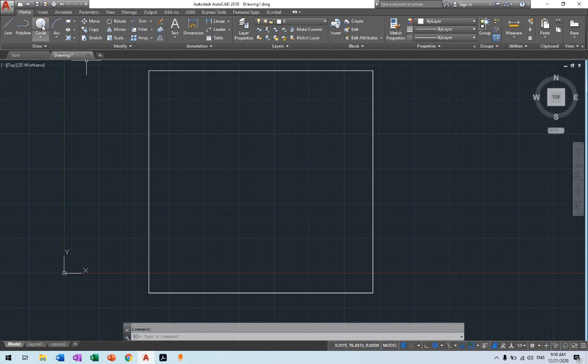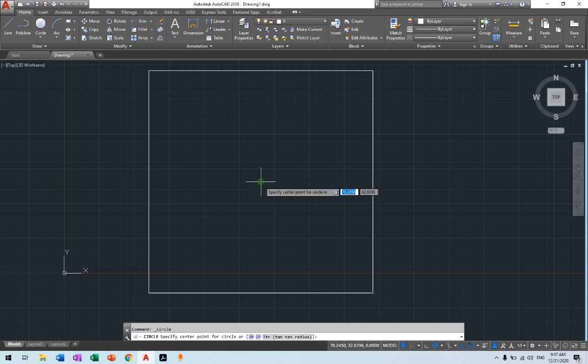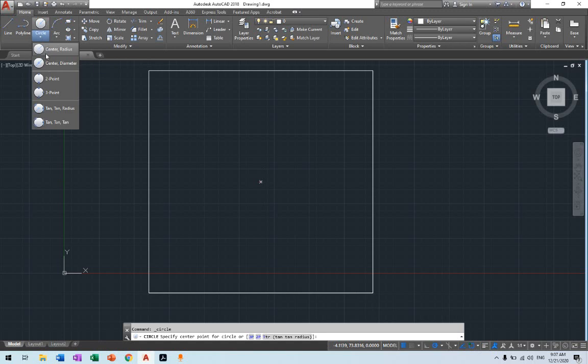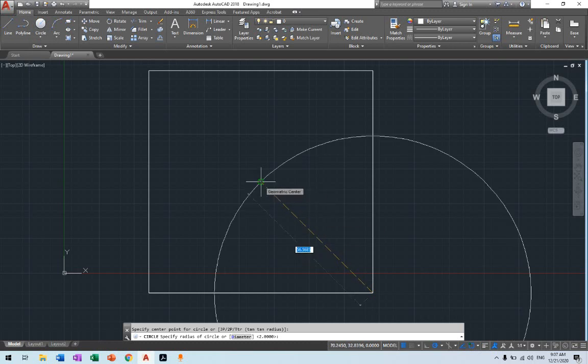Now, we're going to click on the circle. The corner is the center, and since I used rectangle, I can see the geometrical center if geometrical center is ticked in the object snap. From this center till here is the radius. So I can simply activate center radius. This is the center, and I will directly click on here. Why? Because look at the way that we're drawing it. The second point that I click is the radius. So the radius will come here.